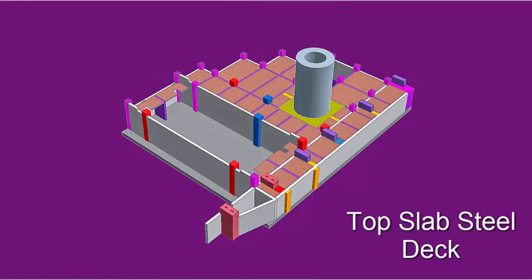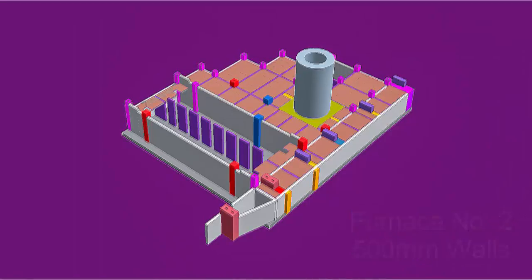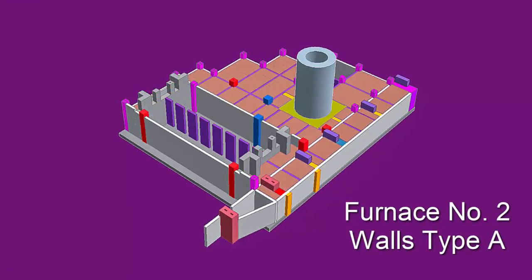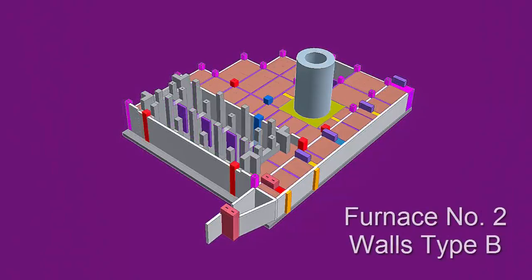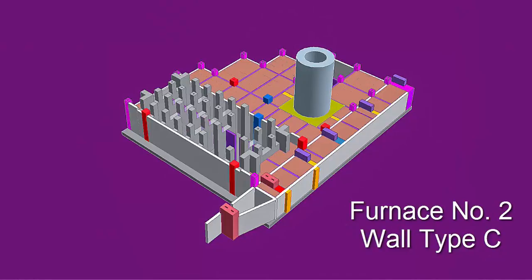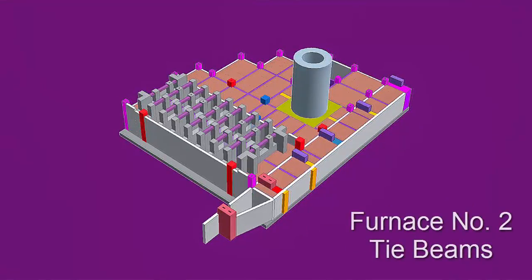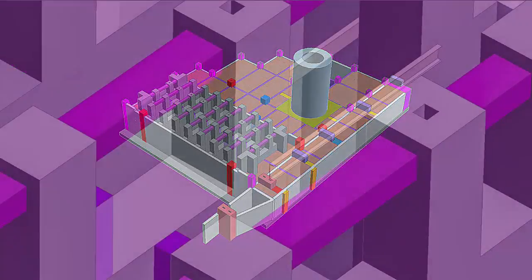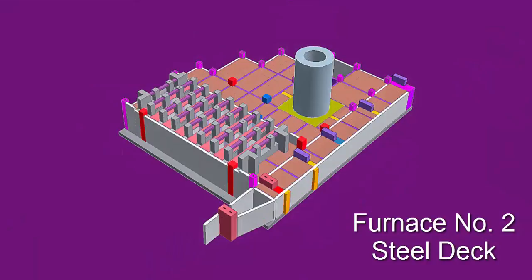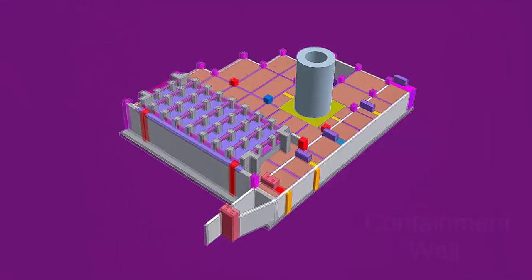An important point to make is that a Revit sheet is not the equivalent of an AutoCAD drawing. An AutoCAD drawing is expensive to create, and a set of AutoCAD drawings are expensive to manage. A Revit sheet is cheap to produce, and managing a set of Revit sheets is much simpler than managing a set of AutoCAD drawings. The AutoCAD version of this foundation had about 60 drawings, with some rebar schedules. My Revit version has 150 sheets. Producing 150 sheets in Revit takes fewer hours than producing 60 drawings in AutoCAD. And remember, the Revit version includes all the quantities.